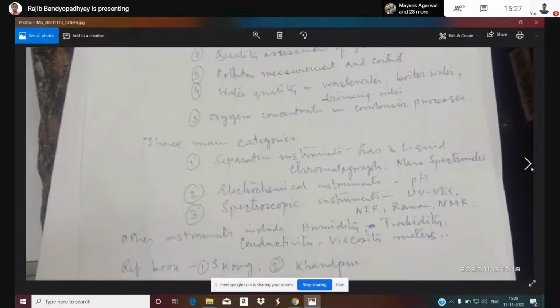But in one application, which is used quite extensively, it is for solids. It is for oxygen measurement. There is no liquid solution. The material used is basically zirconia oxide. Zirconia oxygen analyzers are very popular, although they're quite expensive. They're quite extensively used for measurement of oxygen, mainly in power plants or other places where combustion processes are there.